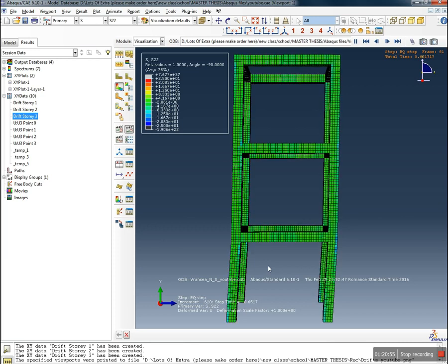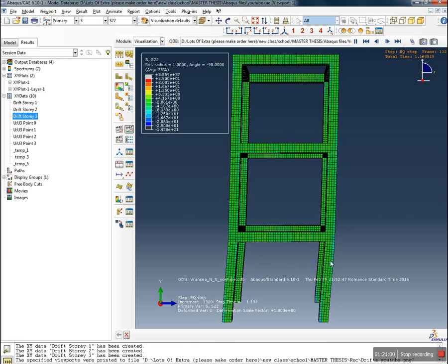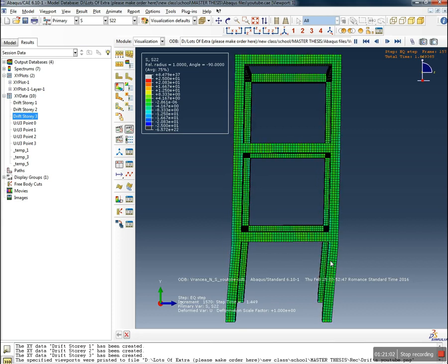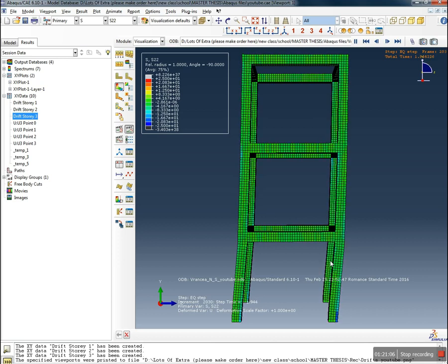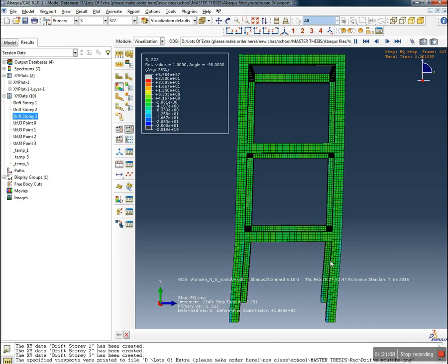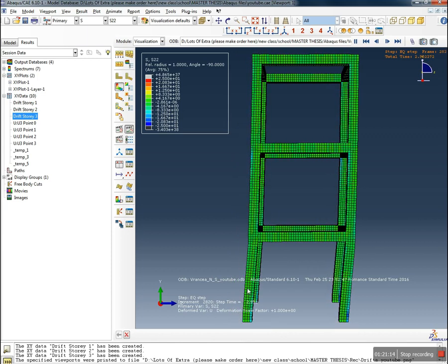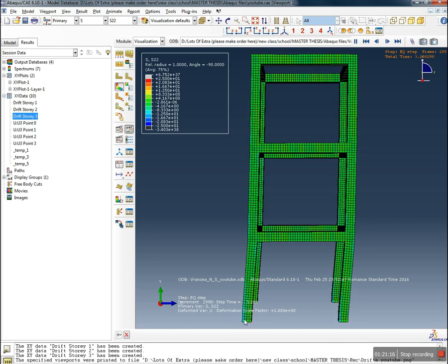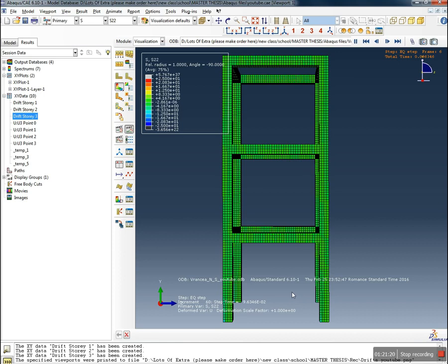They are just some wires, and then you just describe them as square wires with some specific cross section and material properties. That's basically what the stirrups are and how you could define them, and then you can just create one stirrup and create a linear pattern, and you just place them where you want. So that's how it goes with the stirrups.